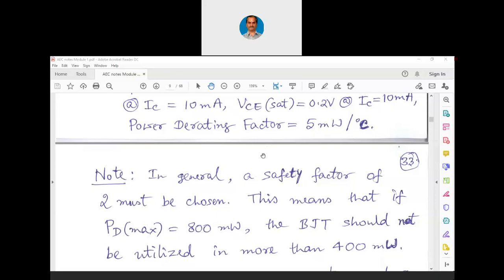You can imagine your own cell phone or a laptop or a computer where there are integrated circuits and components. Even a mobile phone is going to draw 2 watts of power in general, 2 watts of RF power it is going to radiate. It is powered by a battery, and the battery is charged by a charger. Now the devices inside the cell phone should not be used at their maximum power. The reason is, when a cell phone is manufactured, it has to serve our purpose for at least the next 2 to 3 years or 4 to 5 years.